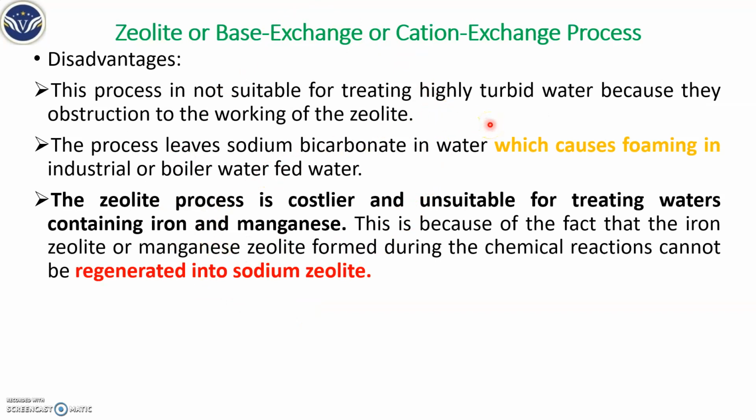If turbidity is more, it provides an obstacle for this process. And sodium bicarbonate leaves a foamy character in the industry and in the boiler, which reduces the efficiency. And the zeolite process is costlier and unsuitable for treating water containing iron and magnesium.